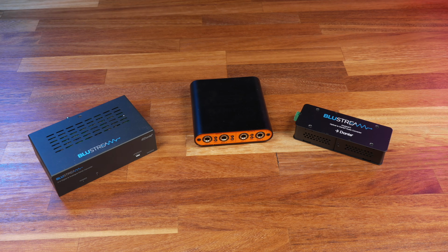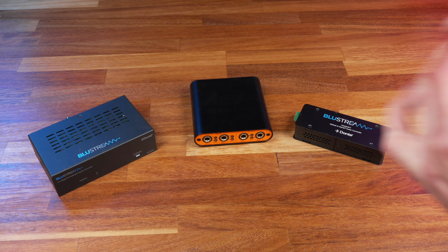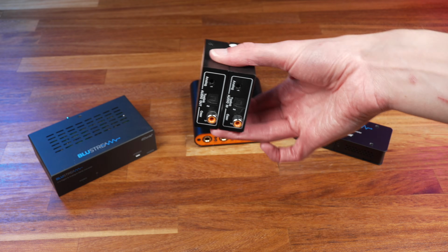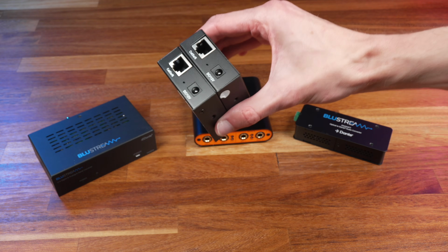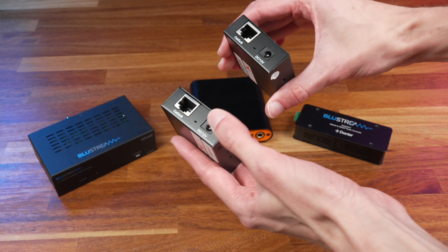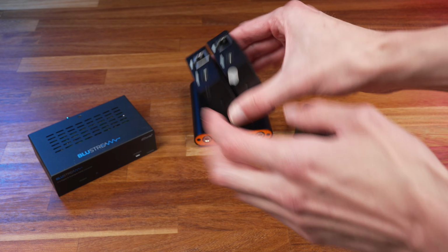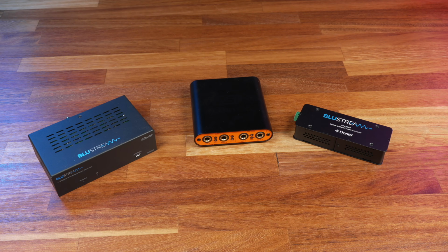So instead of that, I just ran an additional Cat6a drop to each TV, which gives me tons of flexibility. I could use a cheap audio over Cat system such as this to route the digital audio down the regular Cat5 cables. This isn't a network device, it just uses the cable, so you install a transmitter on one end and the receiver at the other, and it sends digital audio down the cable. Alternatively, if I did want to go down the analog route, there are systems that will send a balanced audio signal down a Cat5 cable, and at least with this being balanced, it won't be as prone to interference.